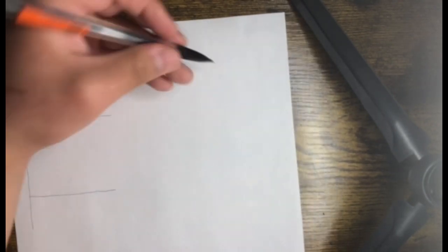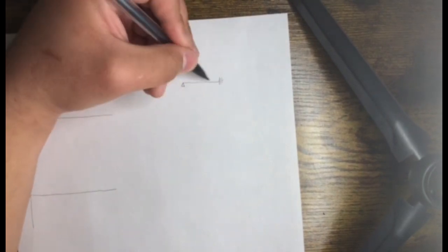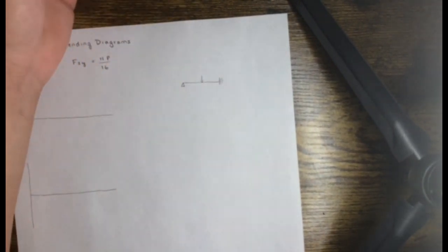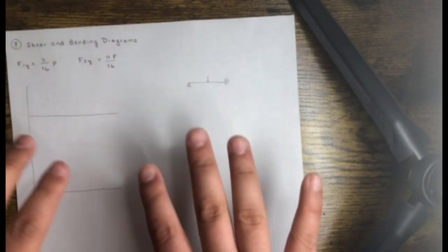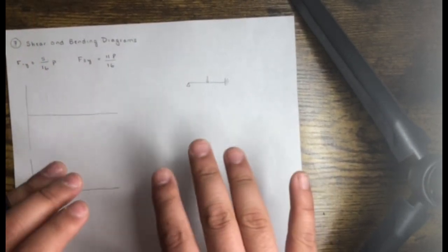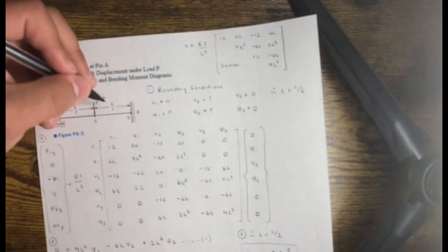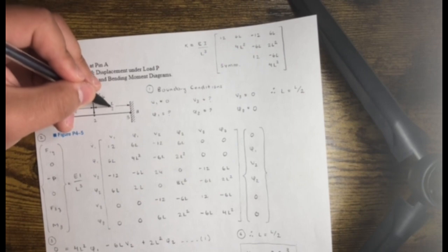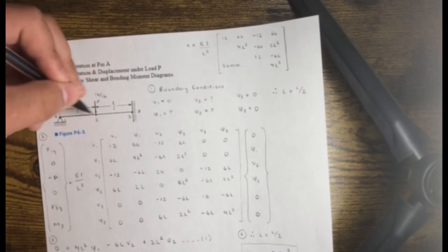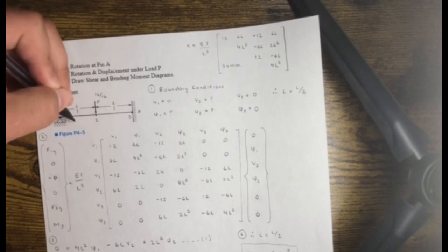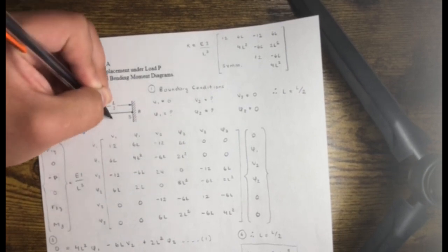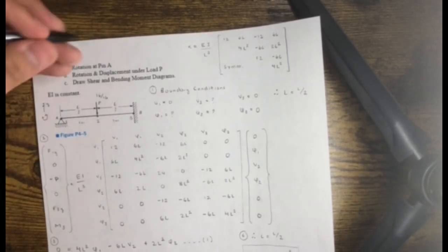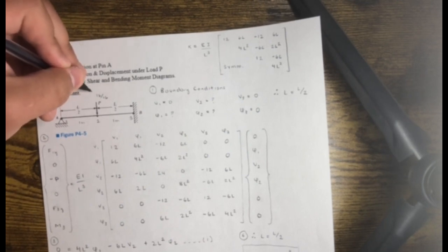All right, so in this case, this is what our beam looks like, just a rough layout. We're fixed here. There's a force P right at the center. It's a little hard doing the bending and shear diagrams for these types of problems when they don't give you values. So let's assume, just to make it easy on us, that the whole beam is 2 meters long. This is 1 meter, and this is 1 meter. Let's assume P is 1, just to keep it simple.